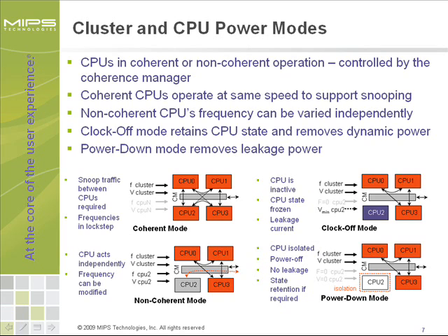The picture below shows CPU 2 has left the coherent address space and operates in non-coherent mode. Bus access for this CPU is supported by the central coherence manager and is routed directly towards higher memory hierarchies, such as the L2 cache. CPU 2 will not receive and emit snoop messages and is allowed to operate at any requested frequency. Voltage for this CPU can be adjusted according to frequency requirements. All other CPUs can remain in coherent operation.